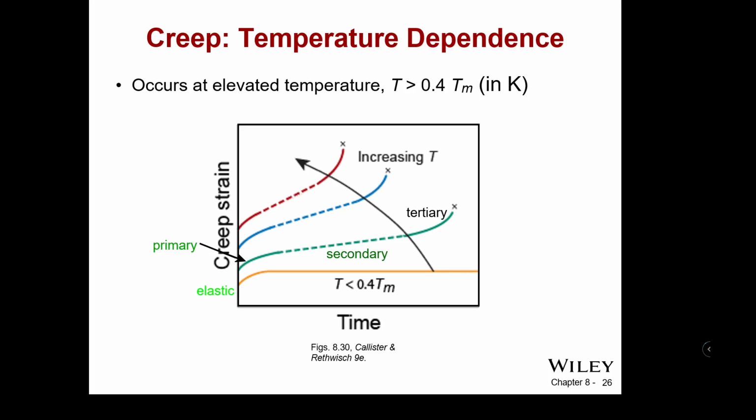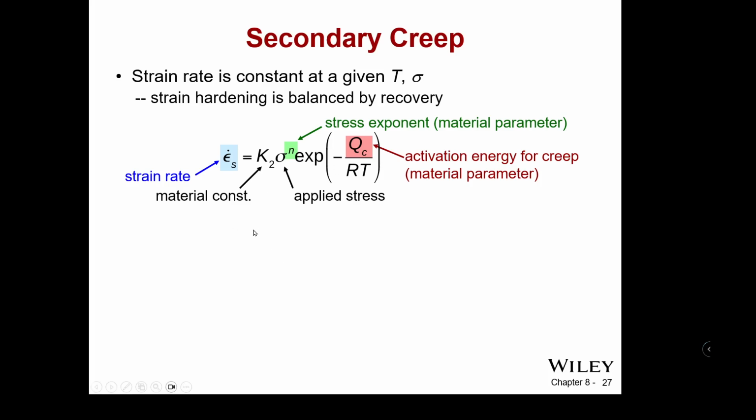The higher that ratio goes with increasing temperature as it reaches the melting temp, creep transitions into flow at the melting temperature because it transitions from a solid to a liquid at that point. And so it continues to increase and increase and increase until at that melting temperature, it's completely, strain is effectively infinite because there is no more change in length with respect to the original length when it does a phase change. There can be secondary creep in a material.